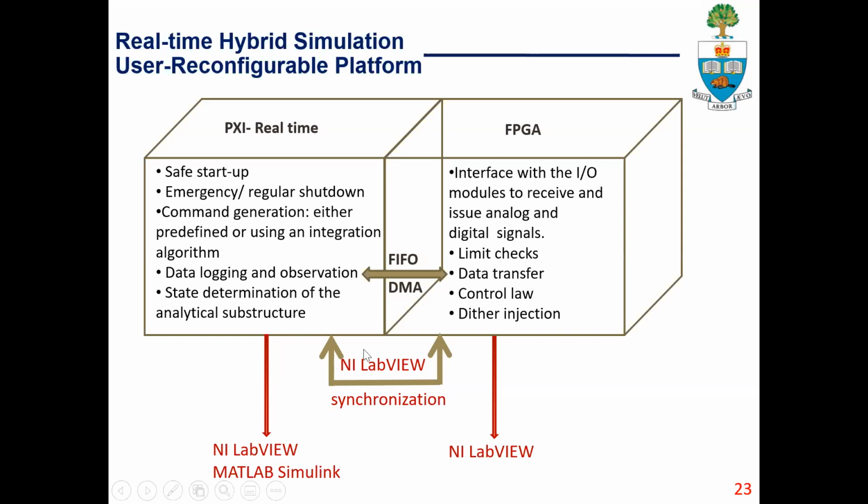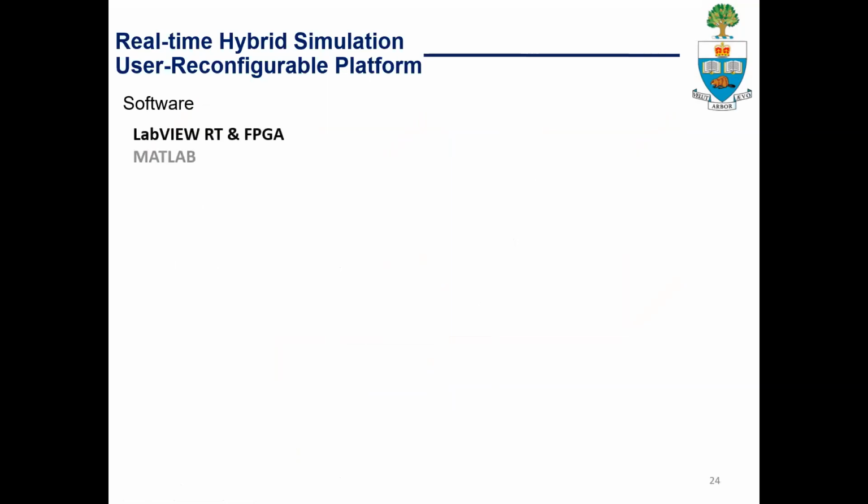And we programmed some of these tasks on the CPU side of the NI-PXI platform, and we provided some of the tasks on the FPGA, and mostly the data acquisition, I/O, and the communication with the input-output modules, limit checks, data transfer, and data injection, and the control algorithm was programmed on the FPGA. And we synchronized the two using FIFO or DMA approaches available in LabVIEW.